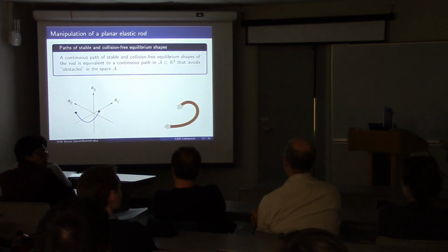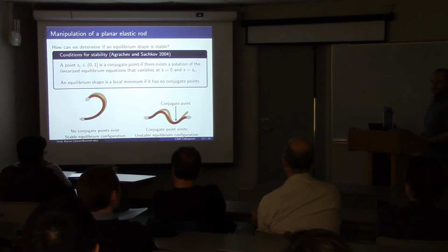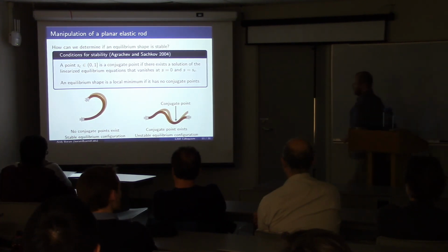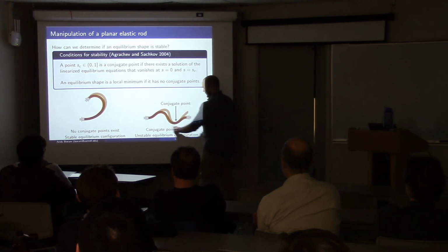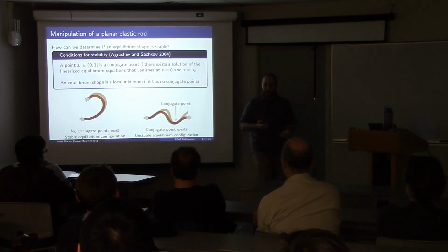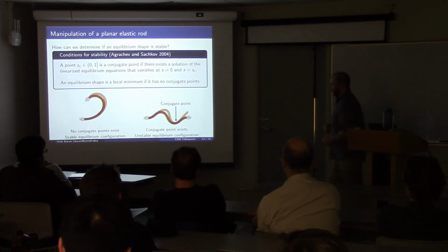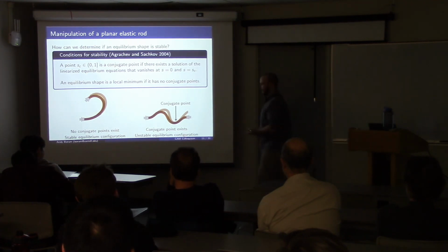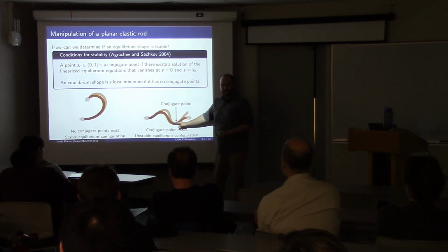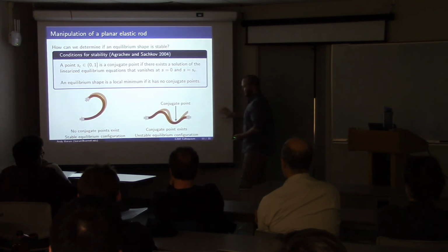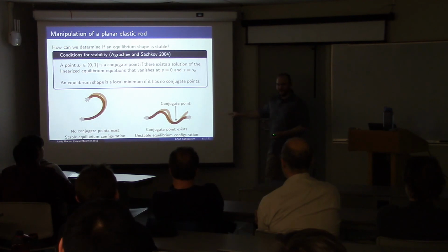Seems like the stability you're interested in has the far end fixed. It looks like you're looking for relations that don't respect that end condition. Right, so one way to do stability is to look at linearized solutions with both ends fixed. That's an eigenvalue problem. You're looking at the sign of your eigenvalues. Morse theory showed that you can just look at the linearized solution. Anywhere this vanishes in here, that corresponds to an unstable mode. If we kept solving this past the end, and this vanished somewhere, that would correspond to a stable mode. So there's a correspondence between those two things.